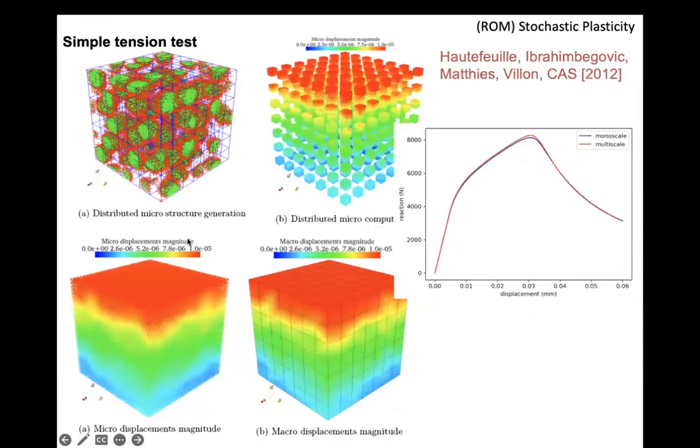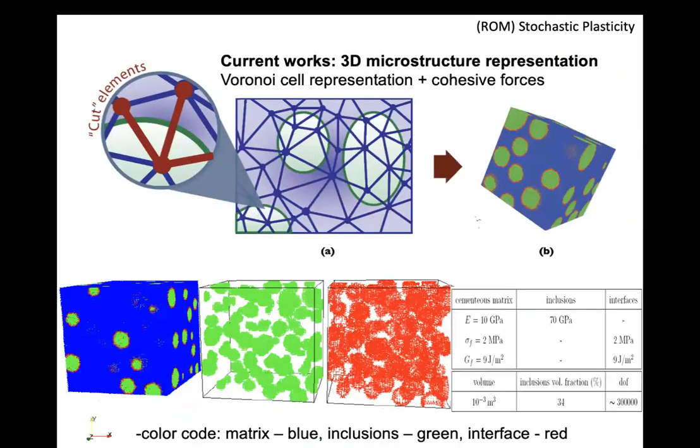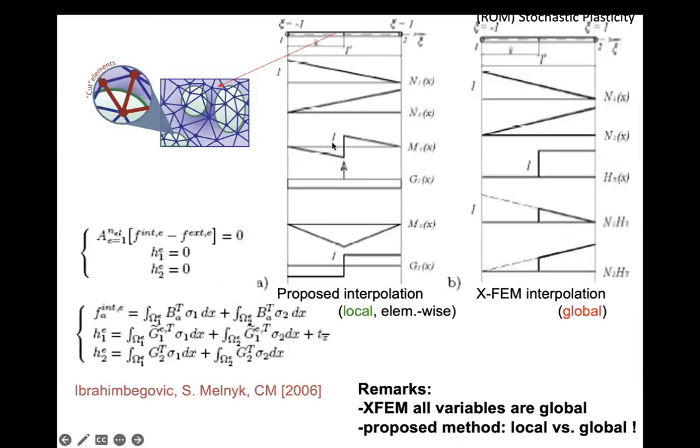So first of all, show that you can do this in the elastic process. You can do this fully multi-scale analysis, no problem with the concrete representative 3D material. You have to do these links that are properly treated with getting the, let's say, correct representation of the strain field with the jumps of the strain field along with the jumps in the displacement field to a localized fracture.